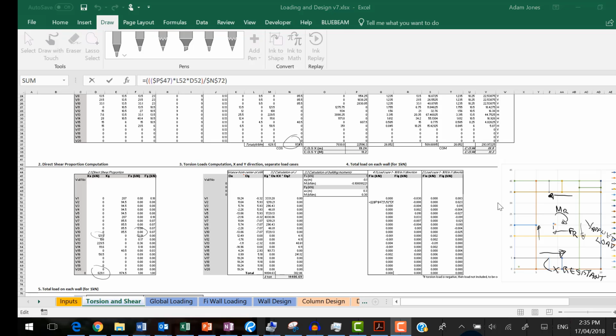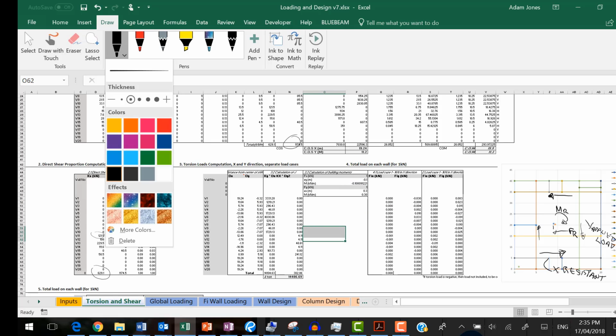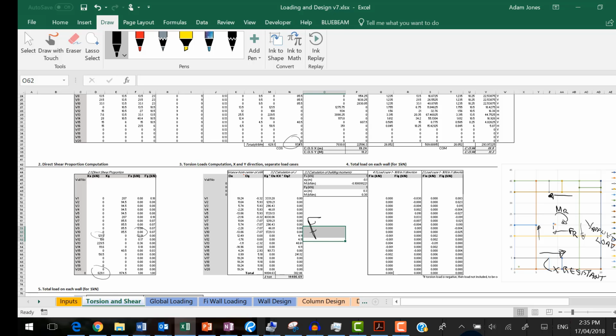So now to get the torsional component on each wall, as you said, it was Fi equals moment times D, or the eccentricity, times K I J divided by the total J. So for the moment, I'll just put down a 1 kilonewton multiplied by EY, so EY being the centre of stiffness, take away the centre of mass Y coordinates to get the moment on the building, and then the D is the individual distance from that Y component.